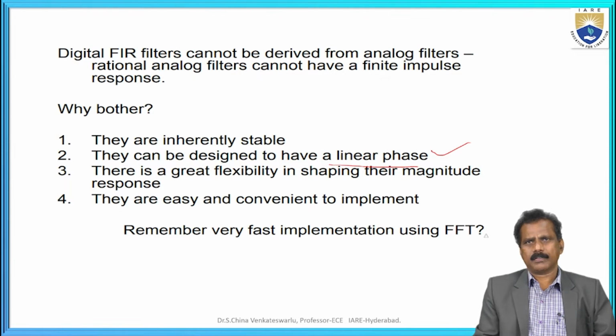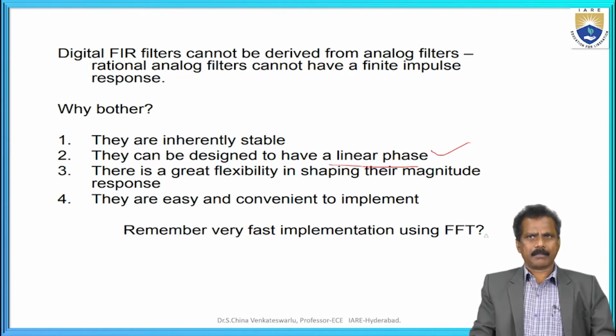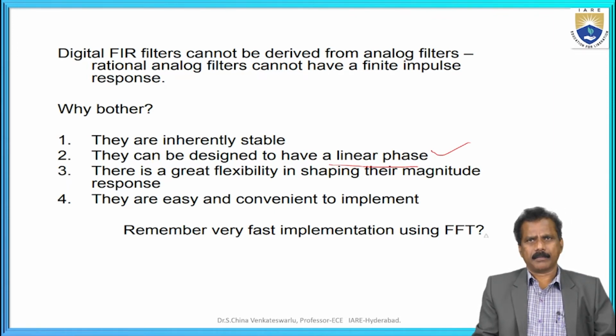So how is it suitable for that? After implementing this design of FIR filter, maybe by using windowing techniques, such as Kaiser, Hanning or Hamming, or sometimes the Blackman window, and so on. After that, we can use the Remez exchange and so on.